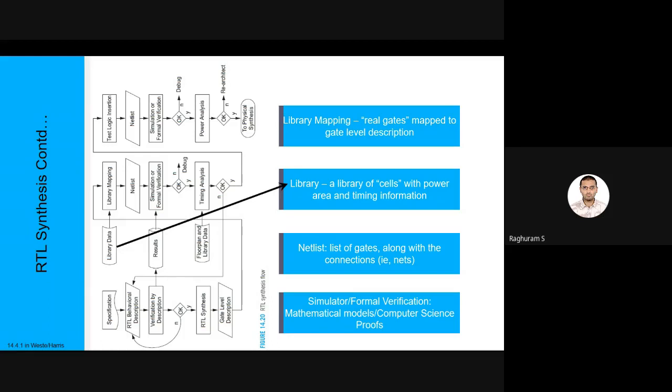So that is what formal verification does. Formal verification even today is not possible for the full chip. Okay, impossible. Full chip you still have to do simulation only. But suppose the heart of your digital system is one particular group of gates which controls everything, and that system has some thousand gates. There maybe you can do formal verification. For a much smaller subset of your full integrated circuit, formal verification is still possible, but not for the full chip.